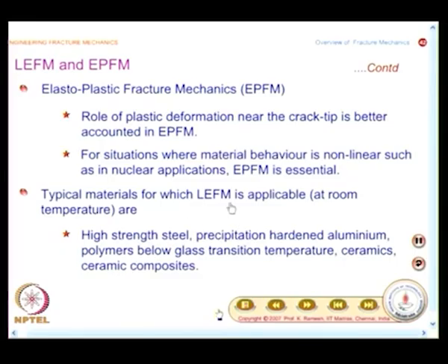When you look at LEFM, if I use high strength steel, precipitation hardened aluminum, polymers below glass transition temperature, ceramics and ceramic composites, for all of these materials you could comfortably attempt LEFM. If it fails, then go for EPFM. These are all thumb rules, not rigid rules. It depends on various factors.